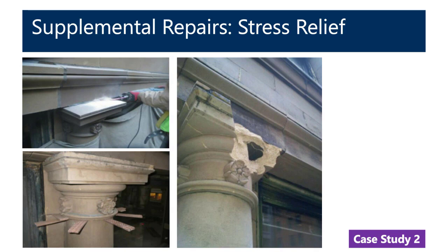Supplemental repairs also involved dealing with additional stress on this building, very typical on full terracotta clad facade buildings. But the thing that is most important to note about this is that they all behave differently. And so they're incredibly unpredictable. And understanding that this oftentimes may be something that you have to stop, readjust, and deal with what the building's telling you. And so for this specific instance, work was being done in another portion of the building, the stress was redistributing, and soft joints needed to be cut, which were never part of the original plan.